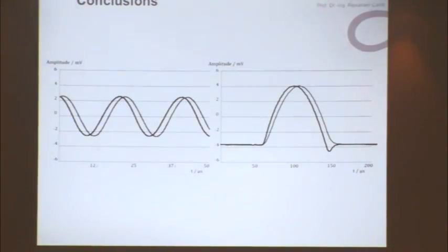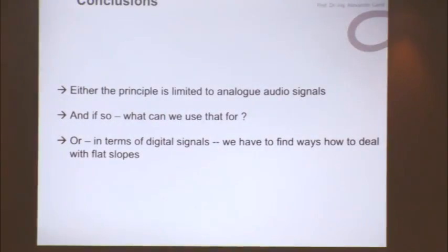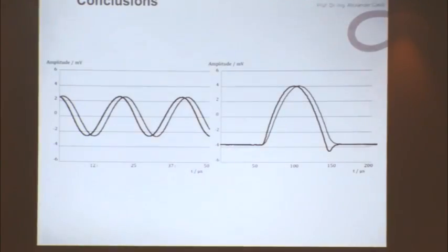So again, with single sines, it's not that problematic, but if we have pulses which start from 0 and have to be back to 0, this implies higher frequencies. And if we are not able to keep these frequencies within the allowable frequency range, we have problems. We have signal distortions.